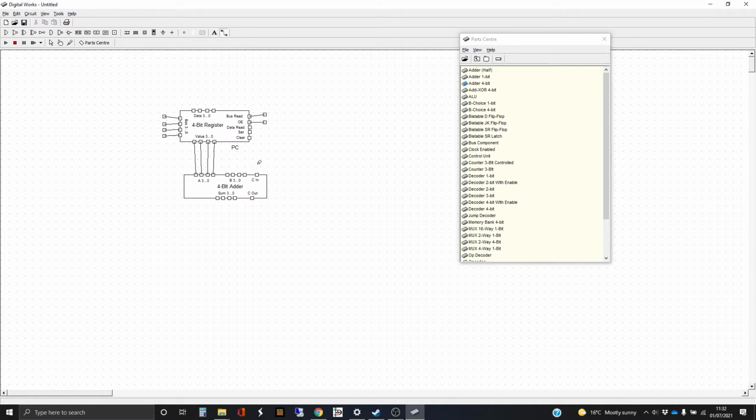And the easy way to do that is to just use the cin, which is the carry in, which will add one. We could just use the lowest significant bit on B as well. That would work equally well. So what I'm going to do is link up the B inputs to ground, which is what this symbol is, which is a permanent 0. And we're just going to make sure that this is a permanent 0, 0, 0, 0 that's being used.